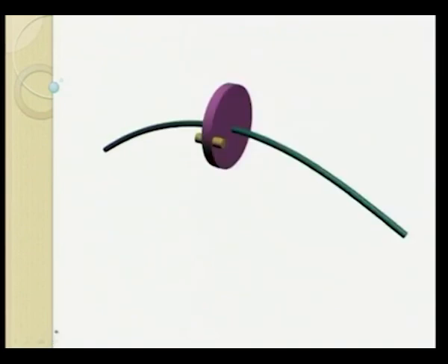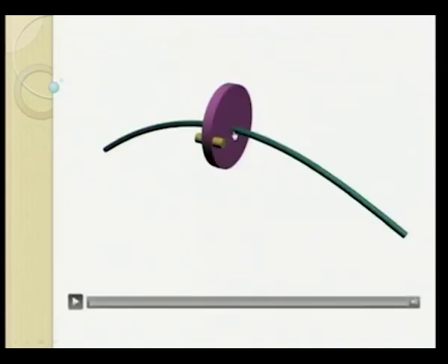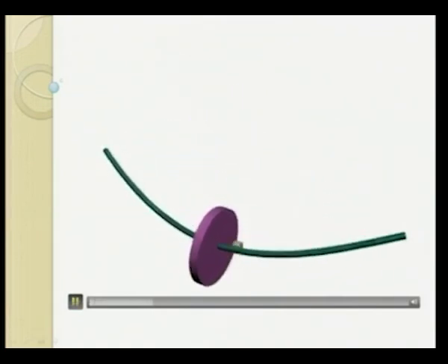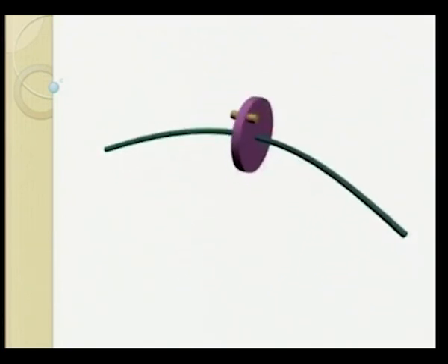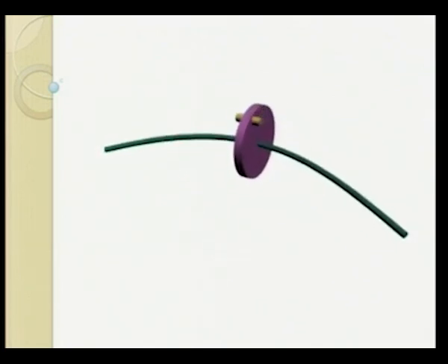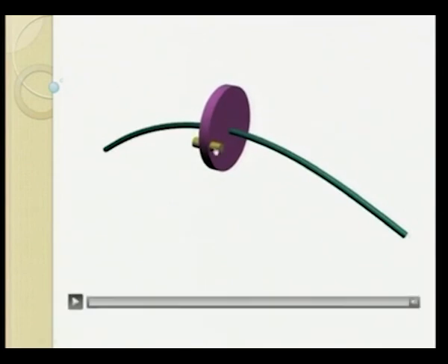And the third case is the one in which we are at the critical speed, and at that position the unbalance is at 90 degrees with the response. Basically this will give a tangential force. You can see the unbalance is always ahead, toward the disc's direction of motion. So this is the critical speed condition, in which the response is in this direction and the force is this. So they have a 90 degree phase difference.